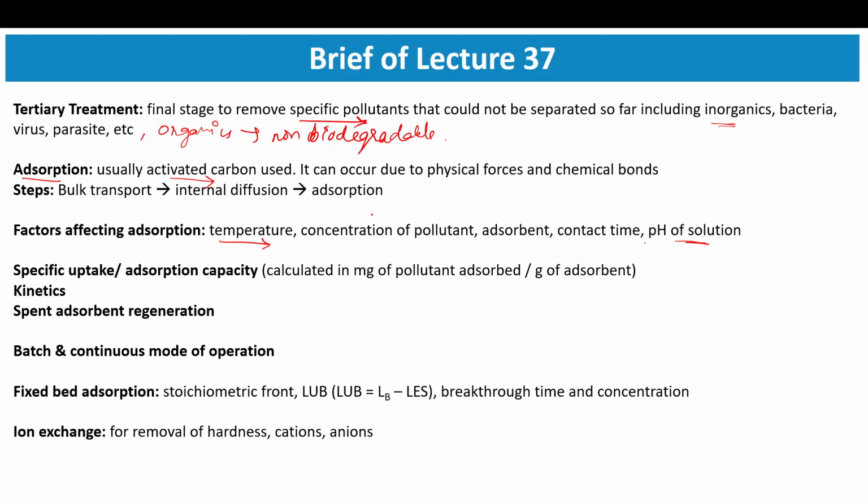Because of the concentration difference, which is termed the concentration gradient. Initially the adsorbent has no pollutant, and only the pollutant is present in the wastewater, so there is maximum concentration gradient.